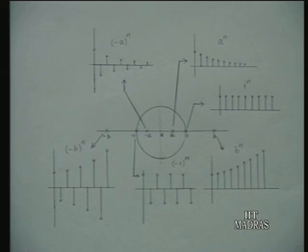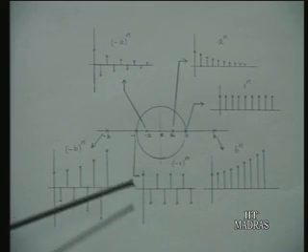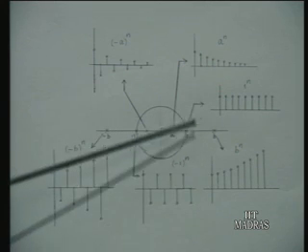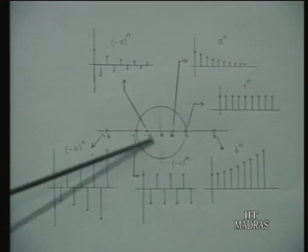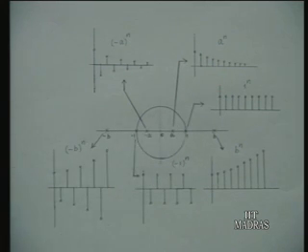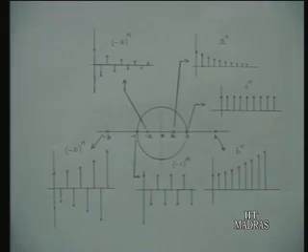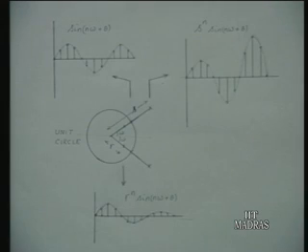So, it is clear from the point of view of stability that all the poles must be within the unit circle, as we have seen here. In this case, the poles here, here and on the unit circle indicate stable response. Let us see what happens when we have complex conjugate poles.